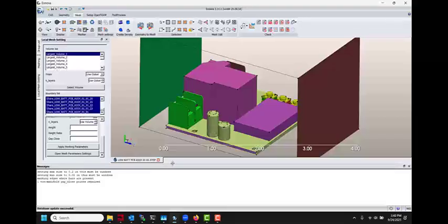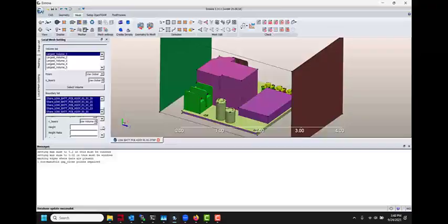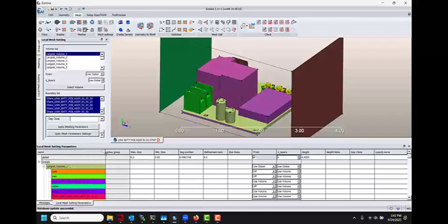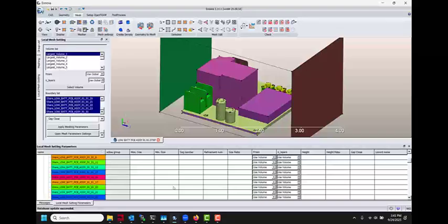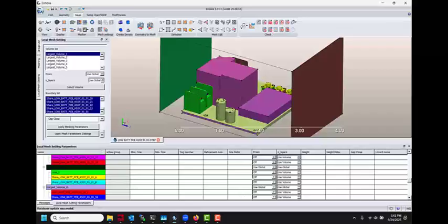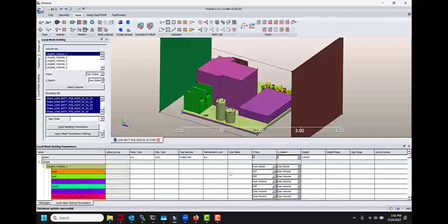So if you're dealing with a lot of parametric models and you bring a lot of the same geometry, we also have this ability here with the open mesh parameter settings to look at what we've just done on the spreadsheet. You can see here's all my surface groups, my different components, and here's the prism control, use volume. And if we look at all the other volumes, you can see it's all turned off. If I right mouse click in here, I can export to XML, or I can save it as an Excel file. Quite often when we're doing multiple runs, it's nice to have all this saved off and just bring it in, especially if we're going to script it later.